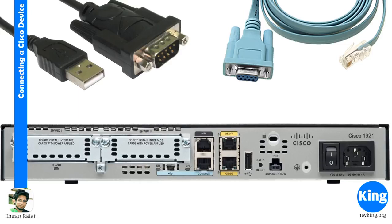So what we need to make use of is a serial to USB converter like the one you see on the left. Once you plug the male serial connector into the female serial connector, and connect the USB port to your computer, you would need to install a USB to serial driver, right? When you install the USB to serial driver, it also installs a COM port onto your computer, and then you can use any terminal software and connect it to your device.